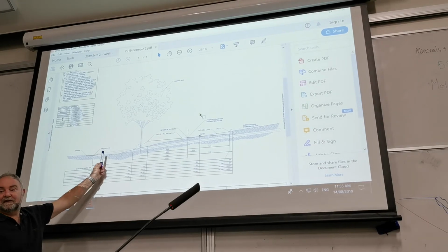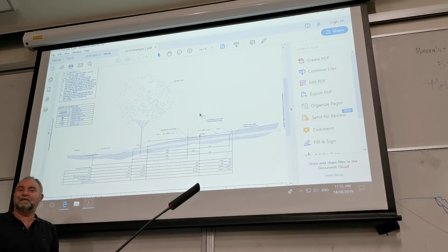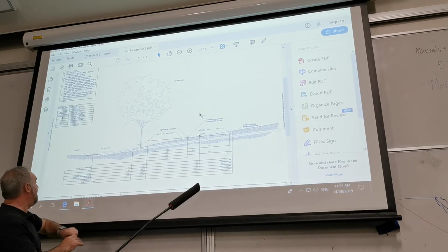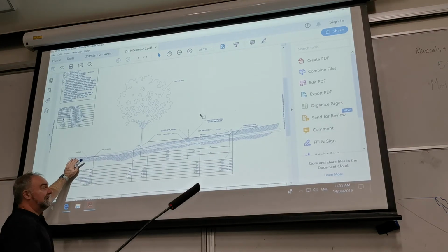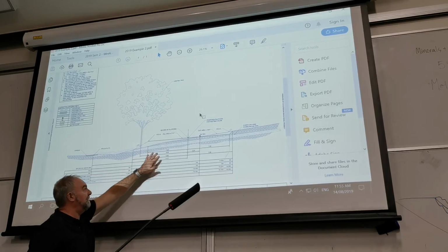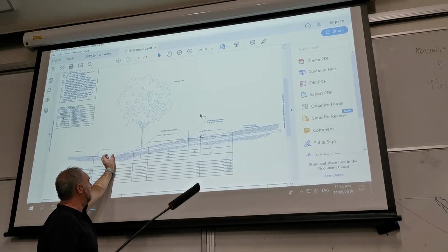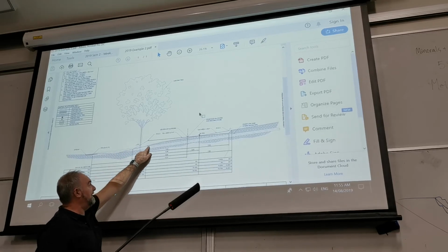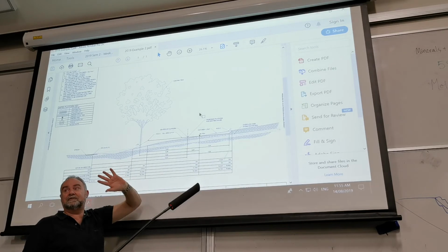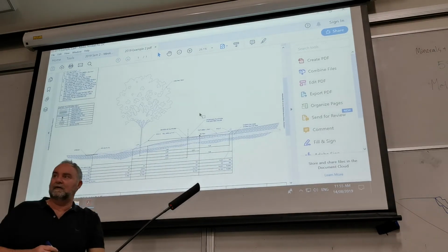Wow, they really did like their basket weaving, didn't they? Absolutely overboard. You only need to show a little bit of it so we know where it is. So for example, here is important, plus on the other side, maybe a little bit under the pipe here and here and here. When I say a little bit, about that much. They've used the batter slope symbol there, completely wrong. It's used on the existing site plan, as per my sketch a week ago.